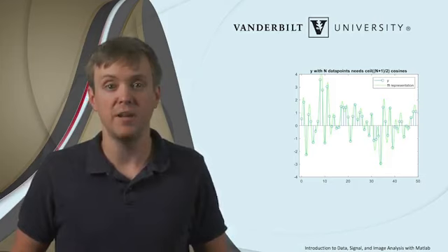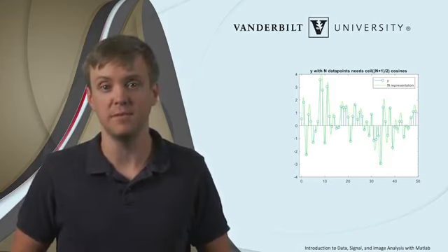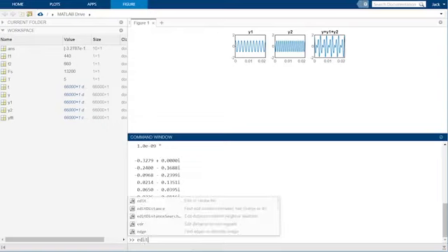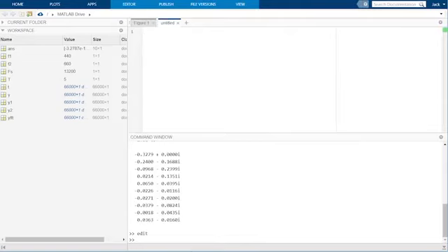Let's go back to MATLAB and demonstrate the power of the FFT. Recall we have a signal y formed by the sum of a 440 Hz cosine and a phase-shifted 660 Hz cosine. Now let's compute the FFT. We will find it useful to write our own FFT function that performs 2 steps in addition to using the FFT function.